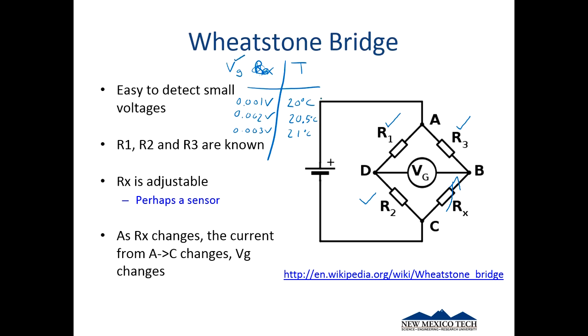look at this voltage. And the nice thing with stuff like an RTD is it's linear, so we can basically take whatever voltage we get here and convert it to a temperature that makes more sense. And so in software there's ways to do this. Idea being you would be measuring this voltage and corresponding it to a temperature. And so this little calibration you'd have to make, but then once it's there, it'll be pretty consistent. So that's the idea with that. Same thing goes for strain, same thing goes for pressure. And so Wheatstone Bridge is going to be really common in instrumentation.